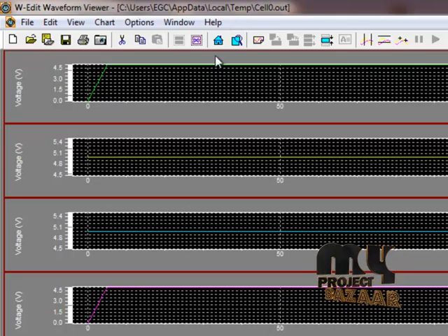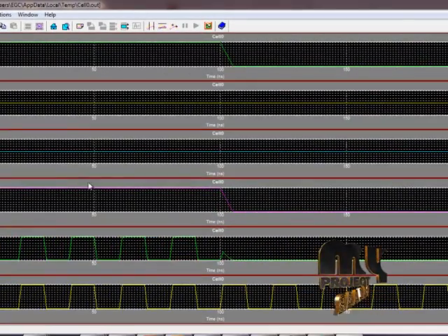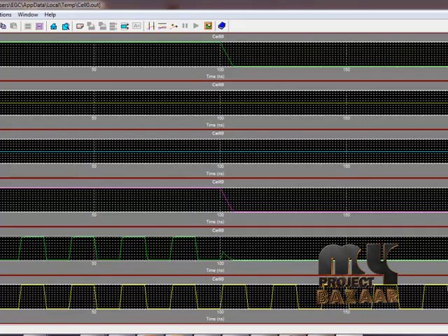So this is the read WL, and this is the feedback line, where we are giving 5 volts. Then WWL is the write WL, and at the same time we choose which port, bit-wise. So this is the write bit line and this is the read bit line. We choose this port, and here we read the process. They give the input of 0s and 1s here.